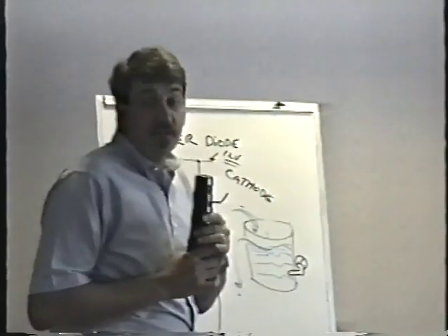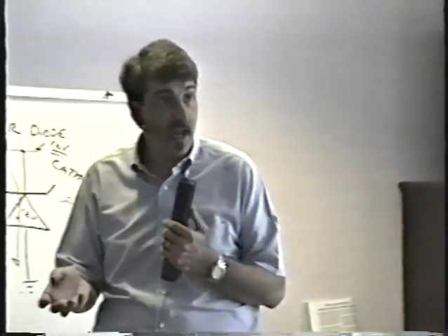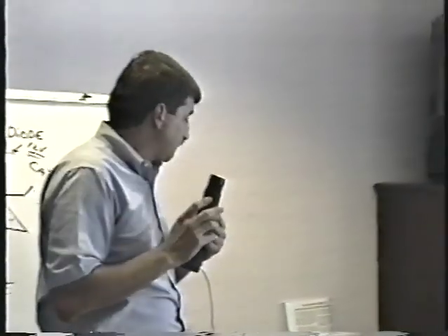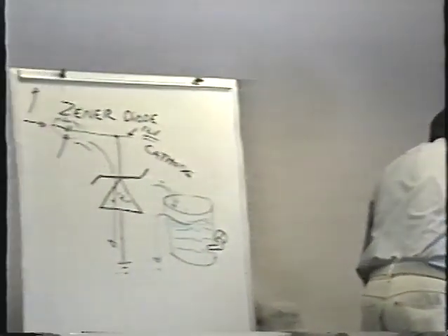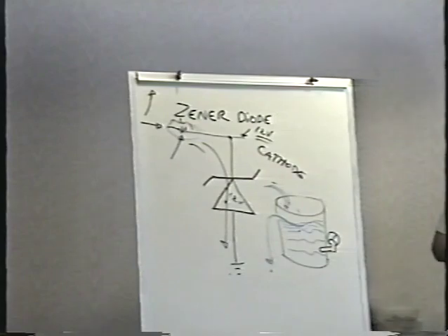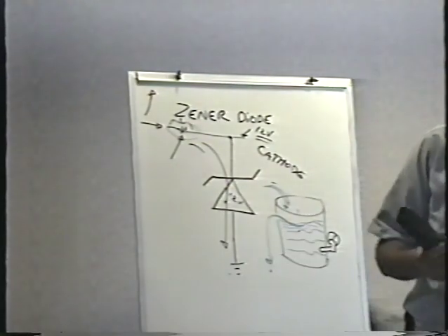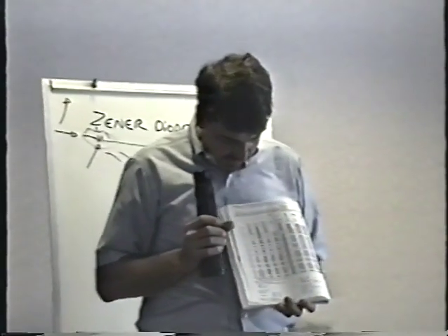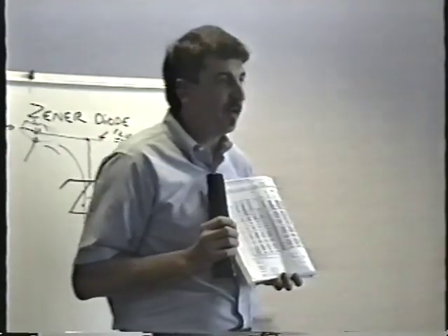Now, when you substitute a Zener diode, obviously you cannot change the Zener voltage. When you look at those voltages, they're very specific, aren't they? 9.1, 8.2, 6.8 is a very common one. You cannot go up in voltage in a Zener diode. You have to keep that exactly the same. But there are two specifications for Zener diodes. If you look back on page R10, correct, Zener diodes do have two specifications. One is the voltage rating. You can't change that. That's got to be the same.